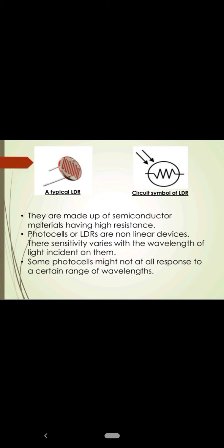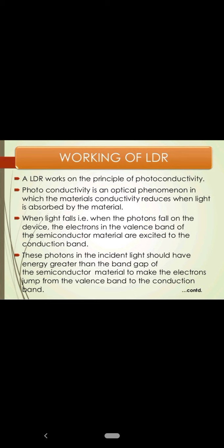LDRs are made up of semiconductor material having high resistance. Photocells or LDRs are nonlinear devices. Their sensitivity varies with the wavelength of light incident on them. Some photocells might not respond at all to a certain range of wavelengths.